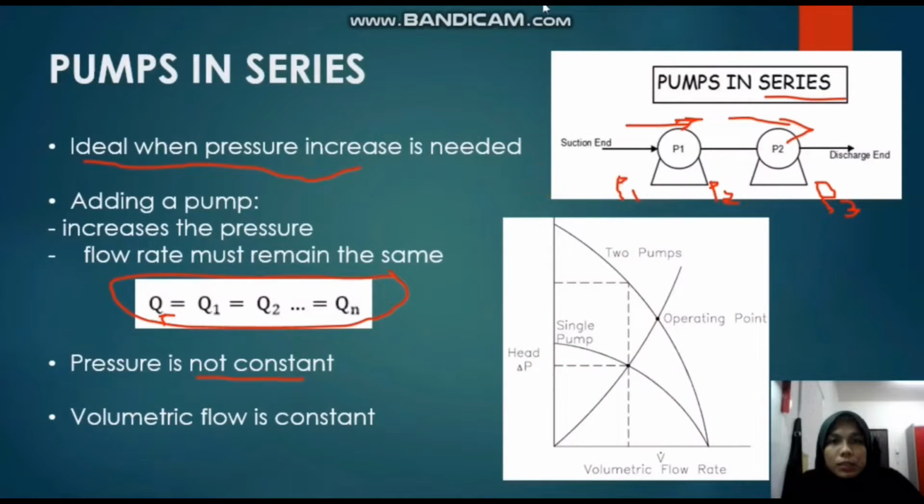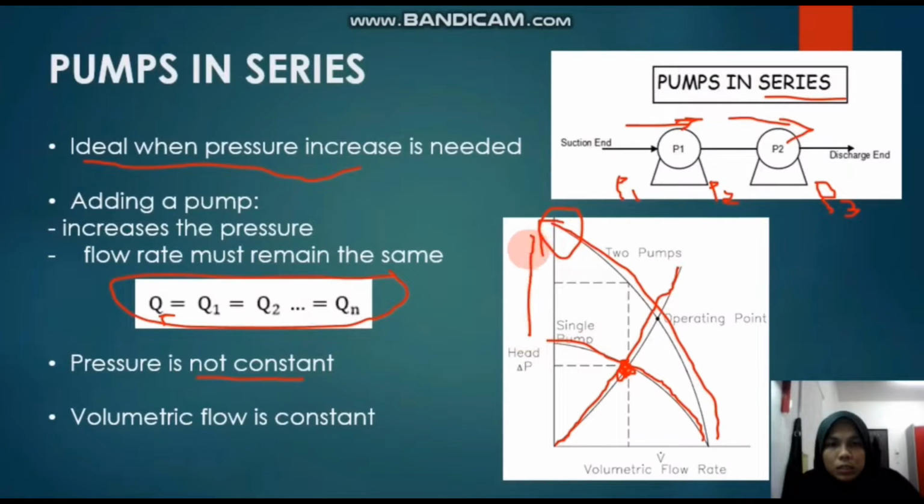So here is the system curve. This will be the single pump, and this point right here is the normal operation. But when the pumps are in series, the head will be increased. The difference.